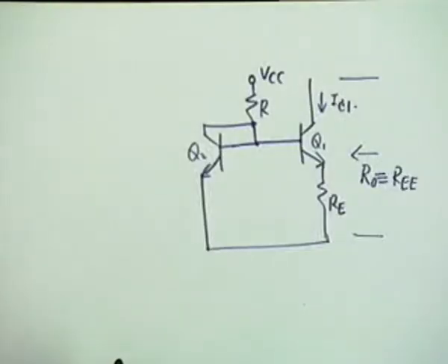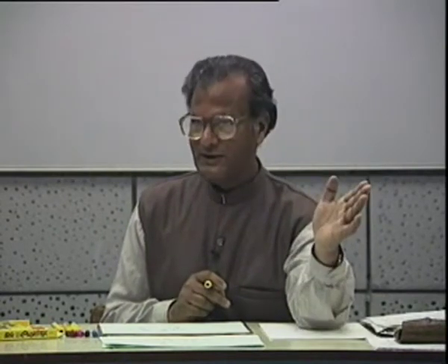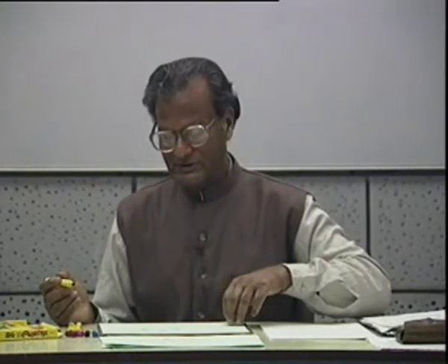And why didn't we increase the lumped resistor? Why did we take help of two transistors? In IC design, we can't use it, because in integrated circuits we cannot go beyond a certain resistor, and the absolute limit is 50k. 20k is honored by IC designers as the limit that they can go, but the absolute maximum is 50k. And if you increase the REE lumped value, we also have to increase what? The power supply, VCC and VEE, which means that there will be much more dissipation in the circuit, and integrated circuits are not designed to withstand heat, because the volume is very small.